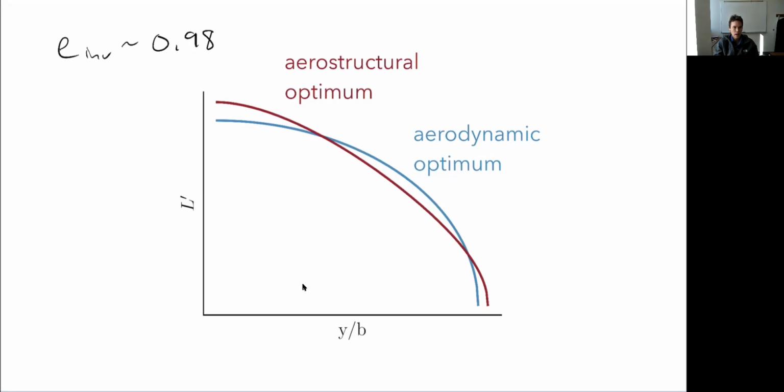So to recap, the two main takeaways, besides a picture of what these semi-monocoque structures look like, is that a thicker airfoil can actually save weight for a bending constrained airplane, which is typical of many designs. And then in general, we'll shift our lift distribution inboard rather than keeping it elliptic. We'll bring it in order to get either a lighter wing, or for a fixed weight, we can actually reduce drag by pushing things out. So thinking about it in a multidisciplinary context means that we usually go a little bit inboard of elliptic.